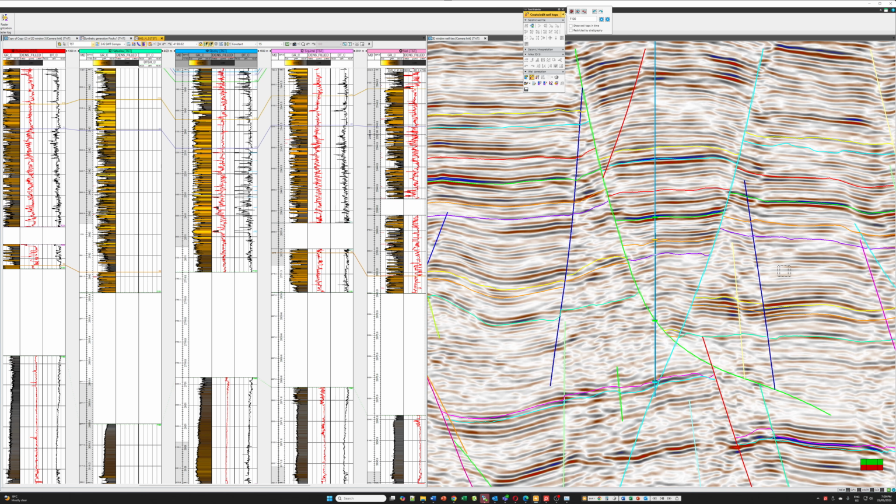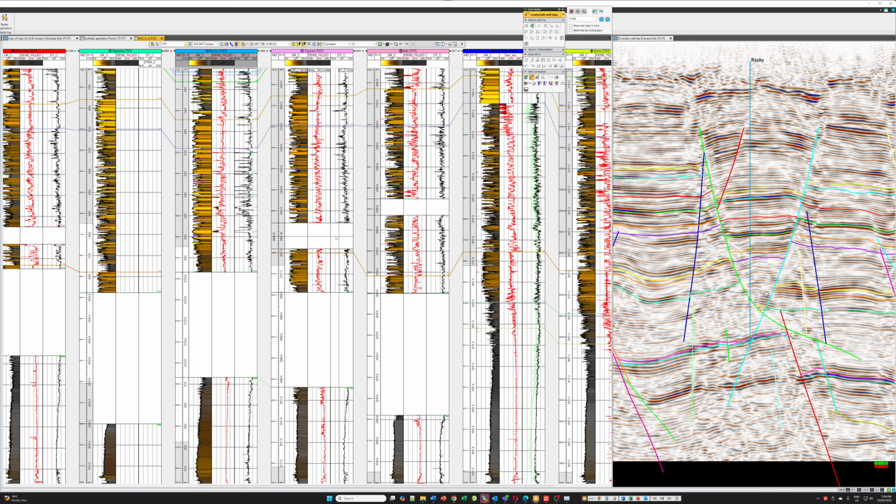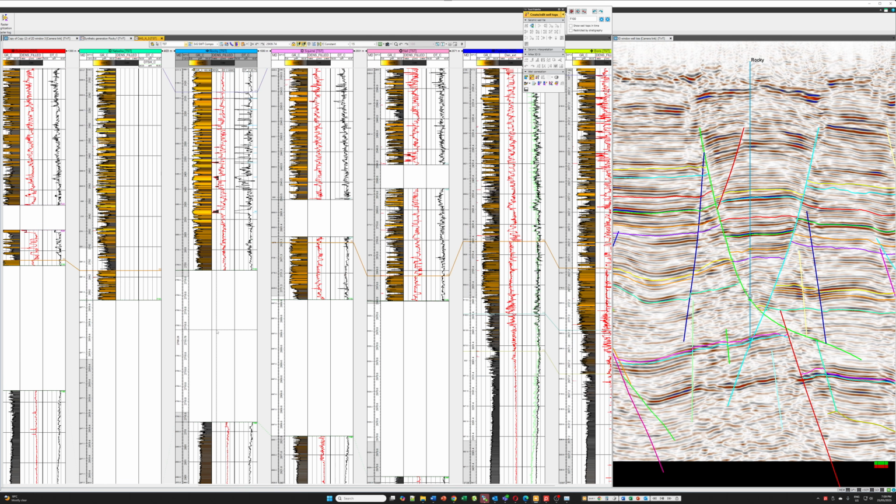When you press run, you will end up with an entry in the global well logs called True Stratigraphic Thickness. Once you have that, you can now turn on True Stratigraphic Thickness in here. Okay, so now you can see I've got the fault in for all the other wells, and I might zoom out a little bit.